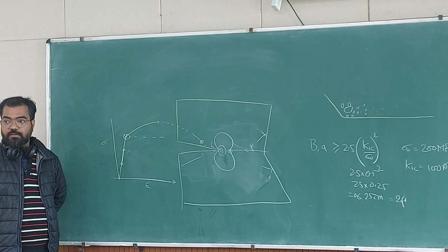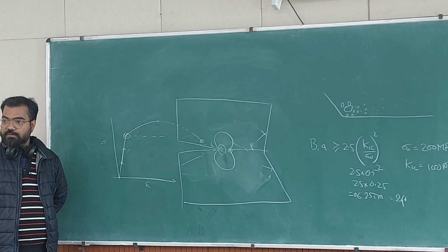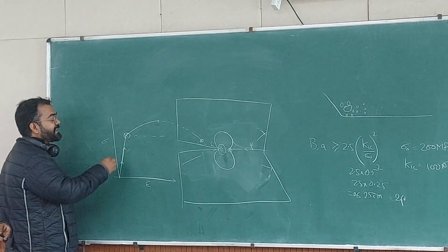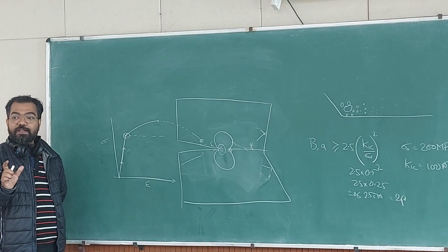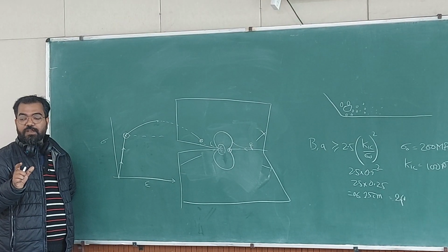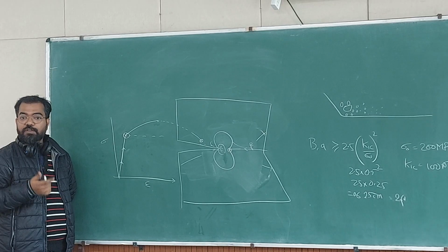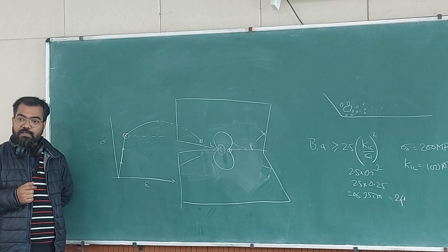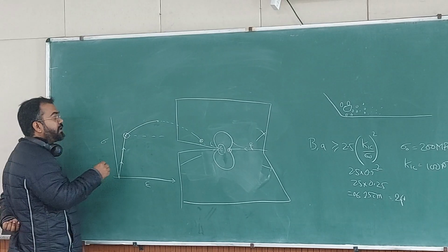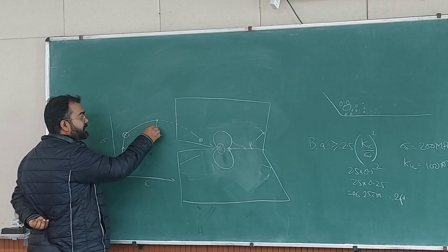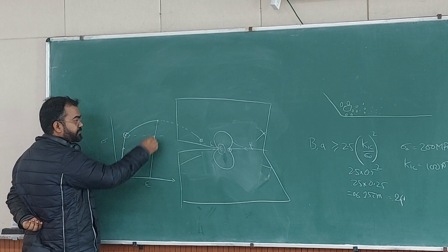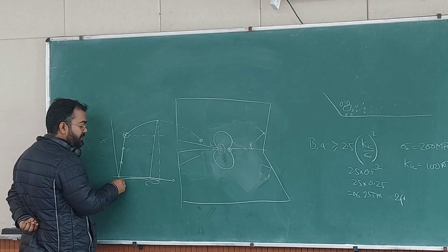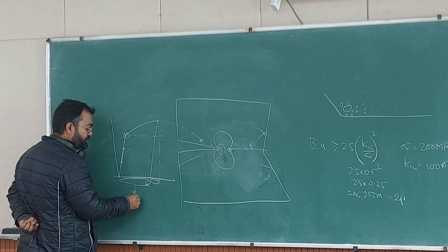So all the strain should recover. Okay, so the difference appears only when you unload. If you keep on loading, then there is no difference between an elastic material and an elastic plastic material. If you unload an elastic plastic material, then it will follow this path, and you will have some amount of strain which is recovered and remaining is not.